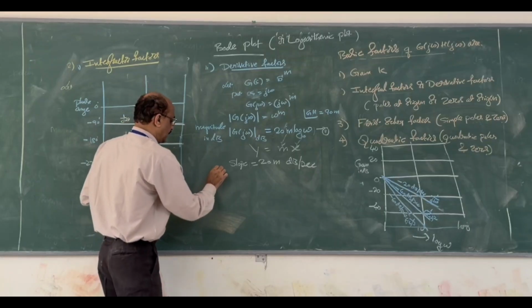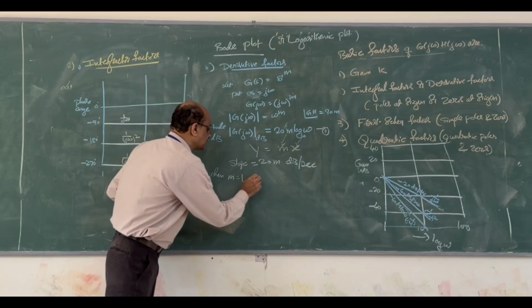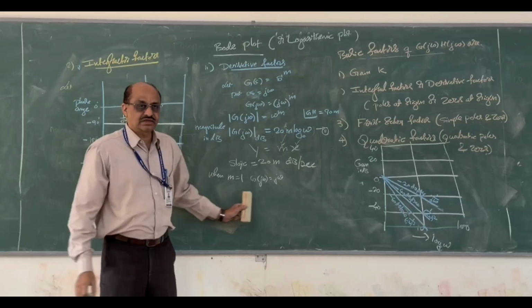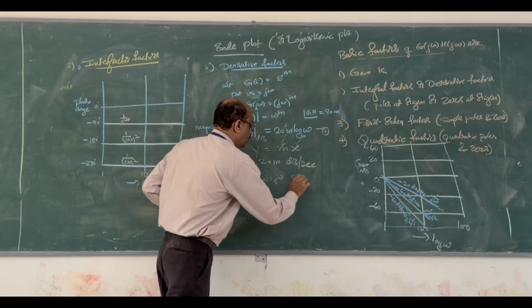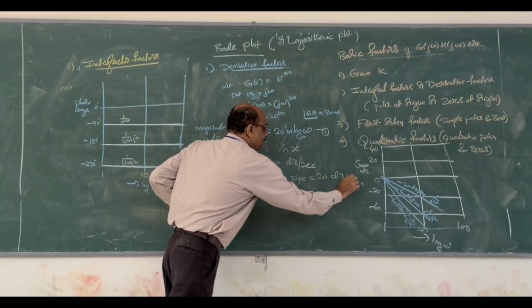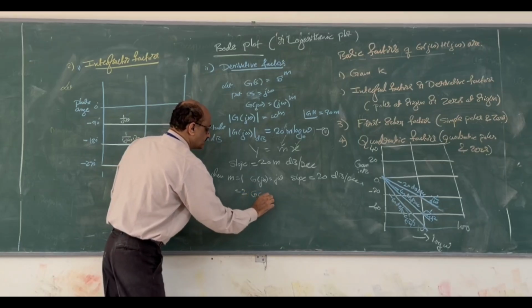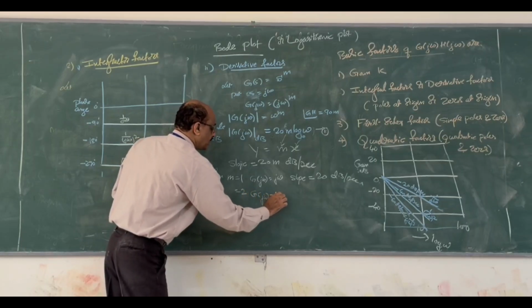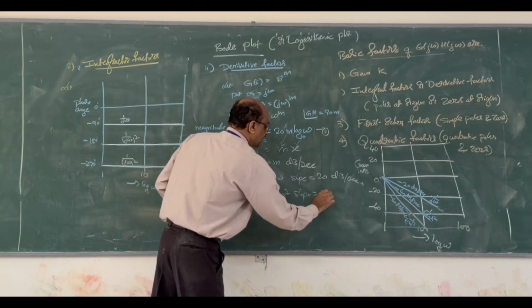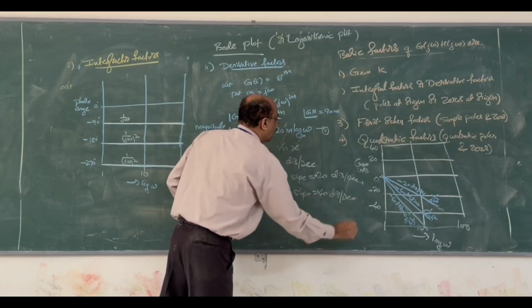So when m equal to 1, that means one zero is there. So G of j omega is equal to j omega. So with one zero there, the slope is equal to 20 dB per decade. Then when two zeros are there, which means G of j omega equals (j omega) squared, the slope is equal to plus 40 dB per decade.